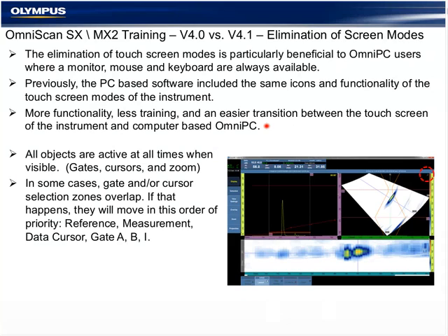And within these two paths, we have defaults available for angle beam, and this would include typical shear wave weld inspection, TOFD inspection, which is limited to the LEMO connectors on the module, and a 0-degree inspection, which is a phased array corrosion mapping or composite aerospace type inspection.